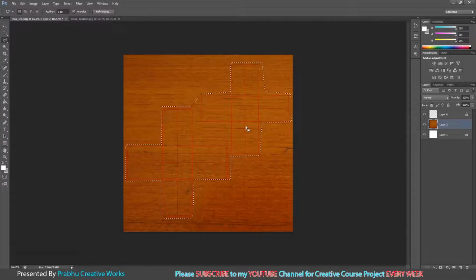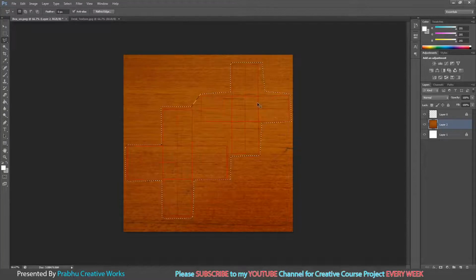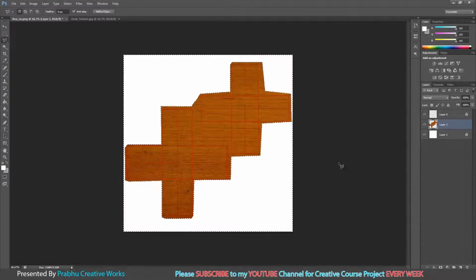Before that, I want to inverse select this object. If I delete now, it will delete the inside, but I want to delete this one on the outside. So use Ctrl Shift I, so that your object will be inverse selected, and press Delete on the keyboard. Now press Ctrl D to deselect the selection. Now I hide my wireframe over here in layer 0.